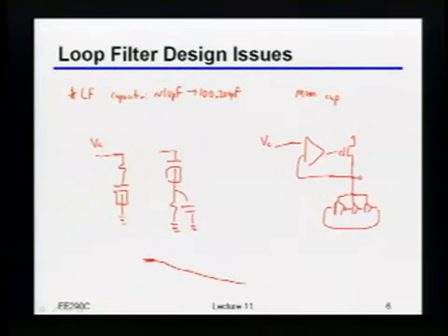Well, if I have a droop down like that, remember, the loop is going to have to make a correction, right? Say, oh, no, oops, sorry, you weren't supposed to be there. It'll correct, and then I'll start drooping down again, right? And then again, I'll correct, right? So all this stuff we talked about, reference spurs, yet another great way to create a reference spur is just to have a leakage path there, right?